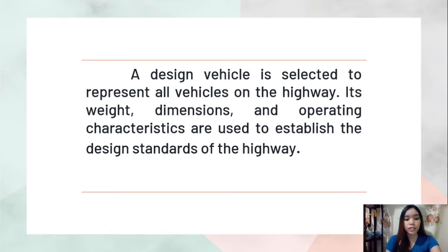The vehicle type selected as the design vehicle is the largest that is likely to use the highway with considerable frequency. The selected design vehicle is used to determine critical design features such as radii at intersections and turning roadways, as well as highway grades.